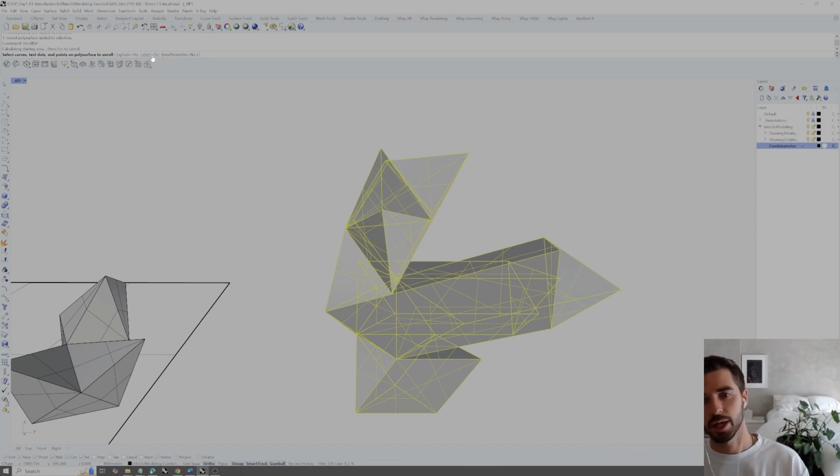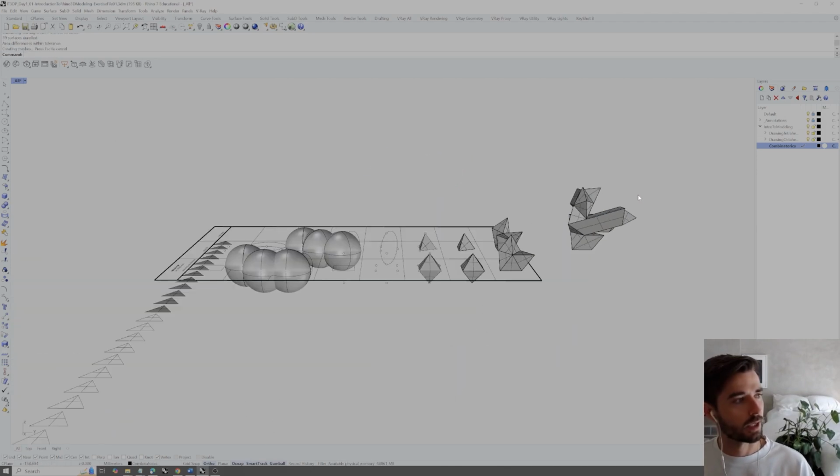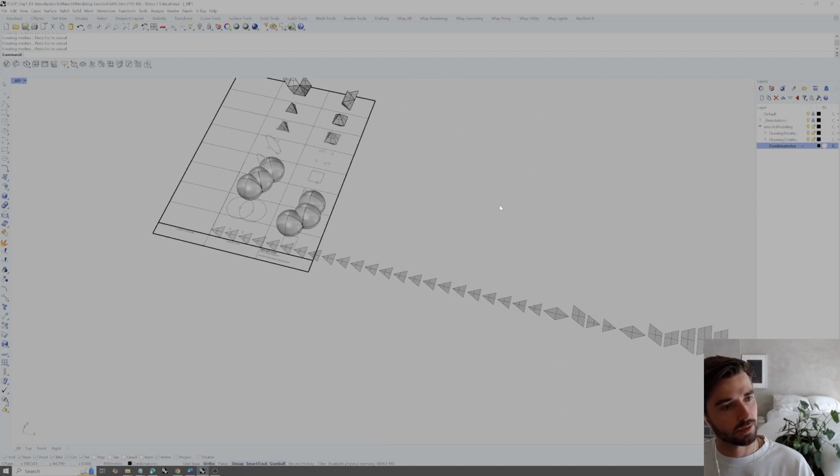Labels no. So labels would just give us which face in 3D matches with which unwrapped face. So if we just leave that at no for now, and then keep properties, we can say yes, it will just keep it on the same layer with the same materials. And later on, we'll get into even preserving the digital texture that we've applied. So if I hit enter, it's going to unwrap each of these geometries exploded and arrayed or laid out from the origin all along the x-axis. So it finished. And now if we click off, we can see each one of those faces arrayed all the way.